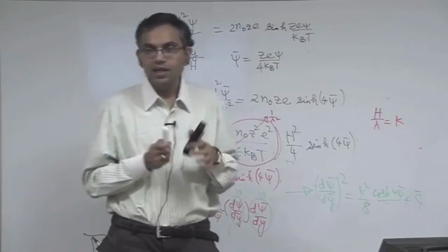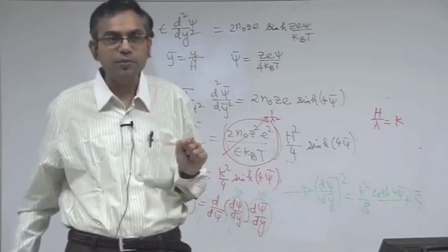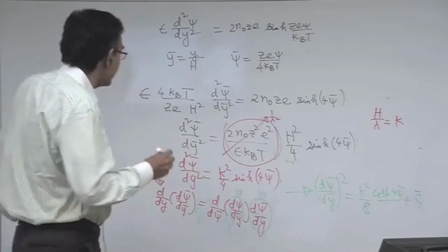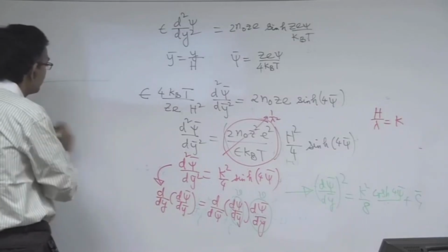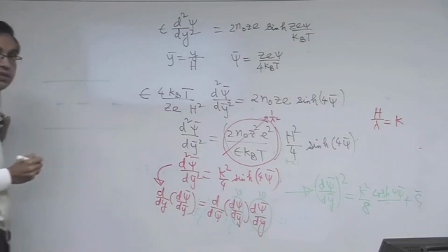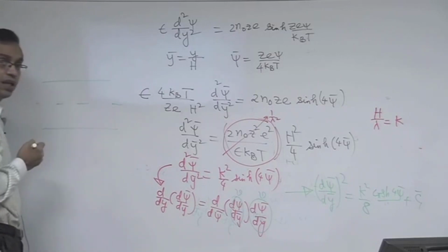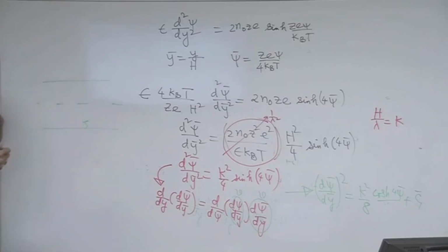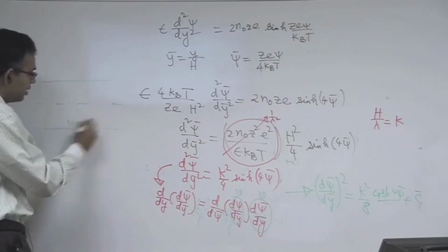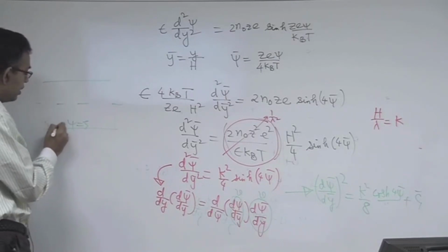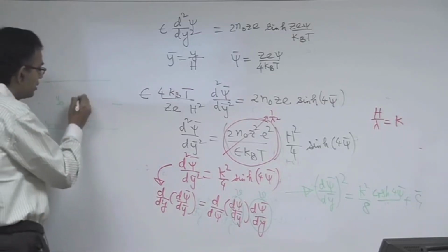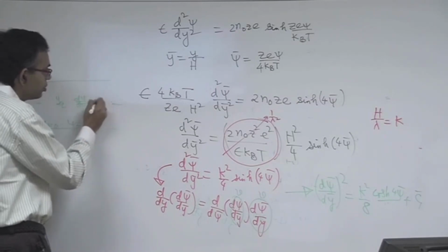But the question is, we have come to a very interesting situation in mathematics. Let us try to understand this carefully. Originally, what are the boundary conditions? Let us say you have the channel, this is the center line. So at the wall, what boundary condition are you giving? Let us say zeta potential, not exactly at the wall but at the shear plane, but let us say it is y equal to 0. At the center line, which is y equal to h, if it is symmetric you have d psi dy equal to 0, true.